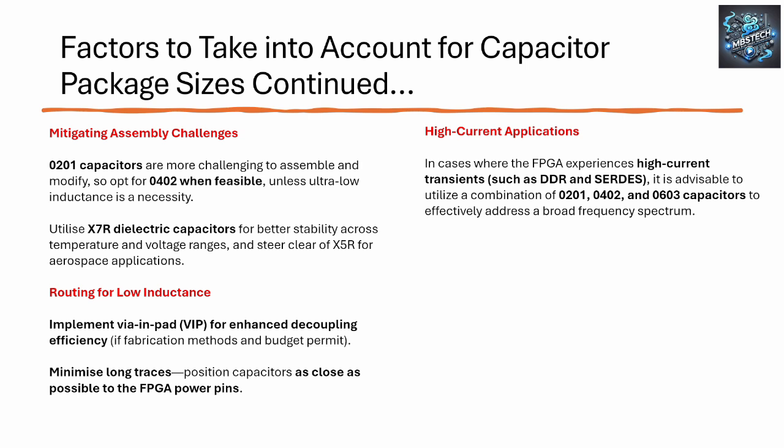So you will get your capacitors underneath. So the technologies tend to support themselves, and the more aggressive parts, especially CPUs these days, they've got on board capacitance, on die capacitance, to help alleviate that challenge for the PCB designer.